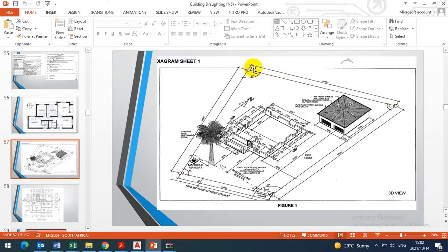These pegs you see, they are diameter 600, diameter 600 pegs before you scale down the drawing. So this is on scale 1:1. You can see they are 31,000 millimeters. This is long. And then this floor plan hasn't got room partitions, but they have given us total length, total width, and the window openings, which you are going to show mostly on the floor plan.